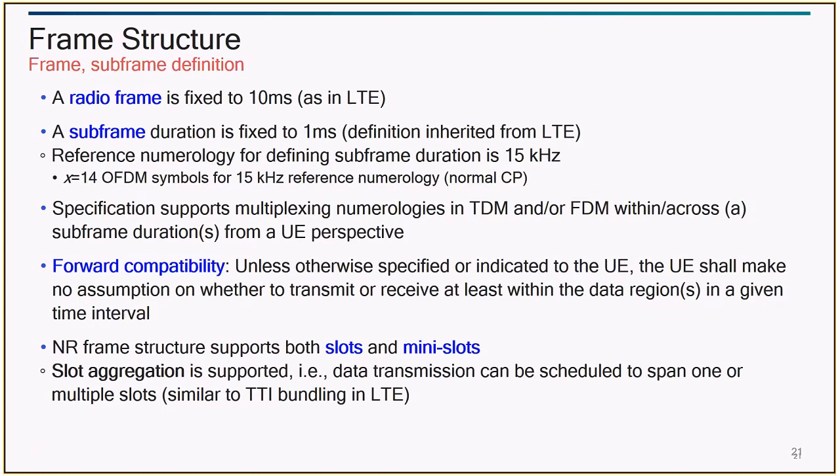That way I have only 2 symbols coming to the UE in 1 millisecond, so only 20 symbols in one full frame, which means I can reduce my speed for a UE. So the same radio frame architecture can work for an IoT environment, it can work for a cellular environment, or it can work somewhere in between as well.